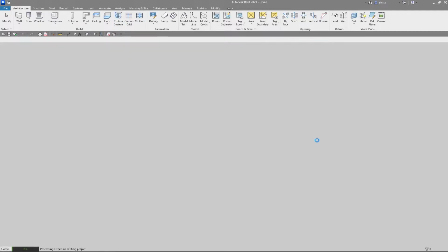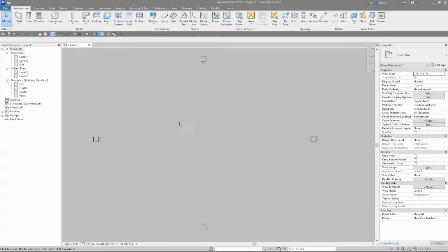It's going to dump us into our default Revit template. Because this is, again, the first video for this course, I'm also just going to quickly review a couple things about the Revit interface, and particularly my Revit interface, and how I suggest that you set yours up. I always take my properties palette, yours will be over here, I think at the top, and I drag that over. You just click on properties and drag it off the right side of your screen, and it should dock to the right side, because I like to have this open at all times and as big as I can get it. It allows my project browser to expand to the whole left side, and again, as I add views and things, I can see them all at a glance.